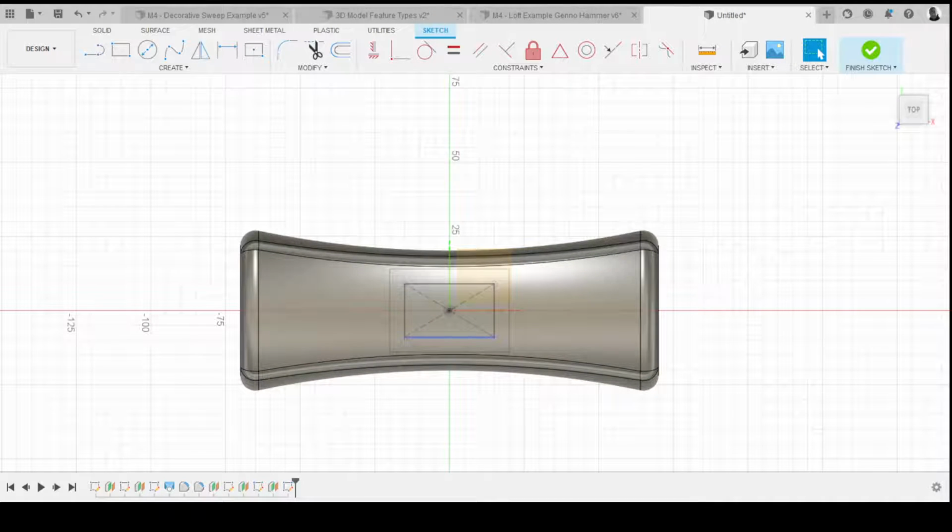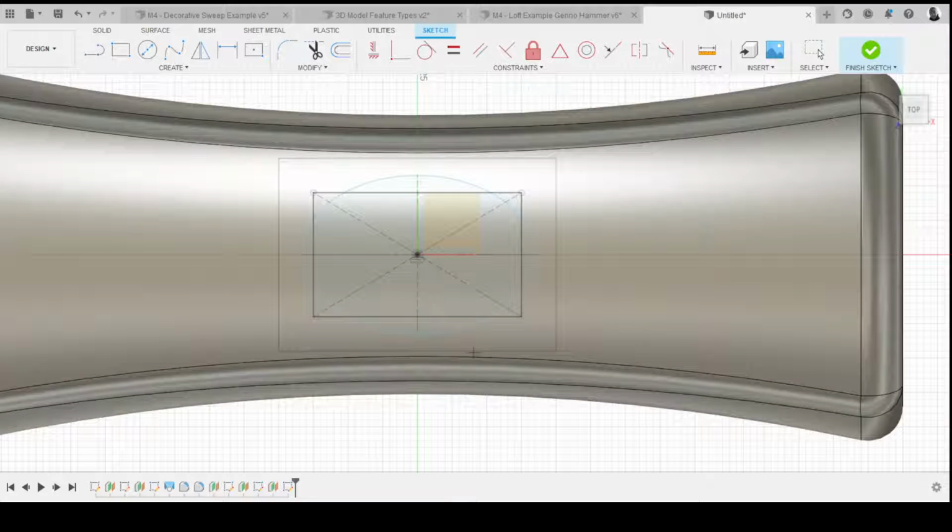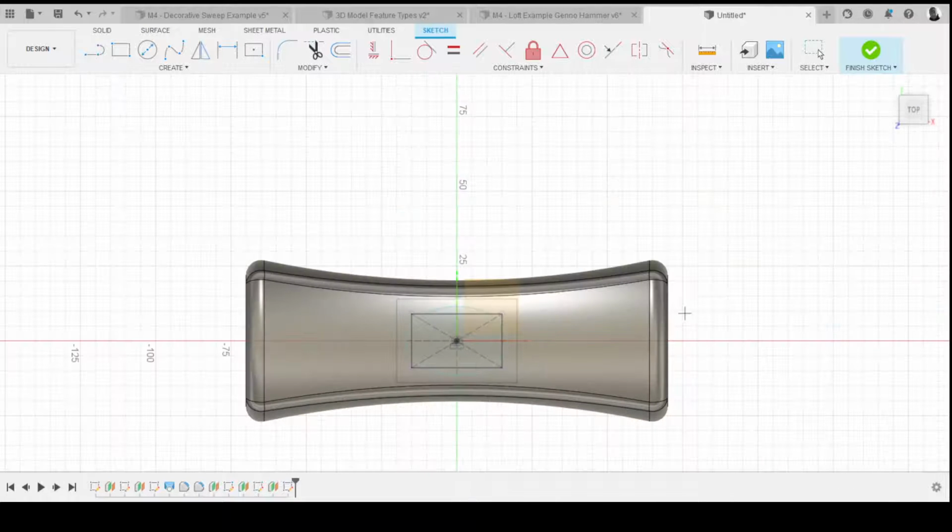And now we're going to use the ellipse tool, which I'm not sure I've shown you yet, but I'm sure you're familiar with. In the Create menu of the Sketch toolbar, about halfway down under Polygon, we've got ellipse. It's just like drawing a center rectangle, so let's click on that. You start off by clicking on the center point of your ellipse, so in this case it's going to be the origin point. Then you click out one line, as it were, for one length or one side. I don't know what the terminology is here. Click it once, and then click it again to get the ellipse that you want. You can define it and give it dimensions if you want to as well, either now or at a later stage. But let's just do a free form ellipse for now. Something that looks a bit like that.